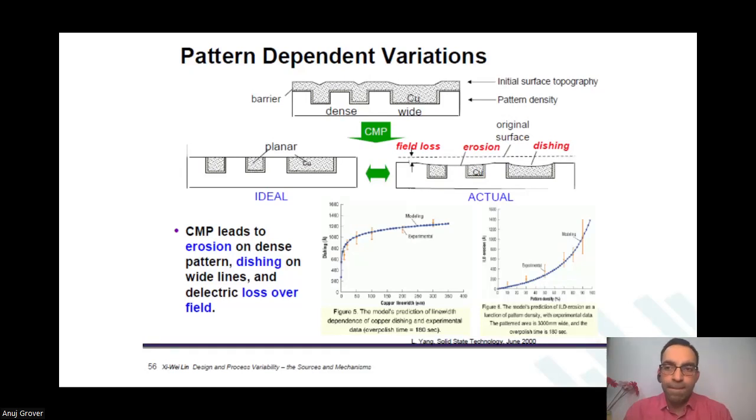Sir, suppose we consider the case of denser wires, the dishing will be less, but intrametal capacitance will increase now. So RC also increases. Resistance is lesser because the wires are taller, but capacitance increases.